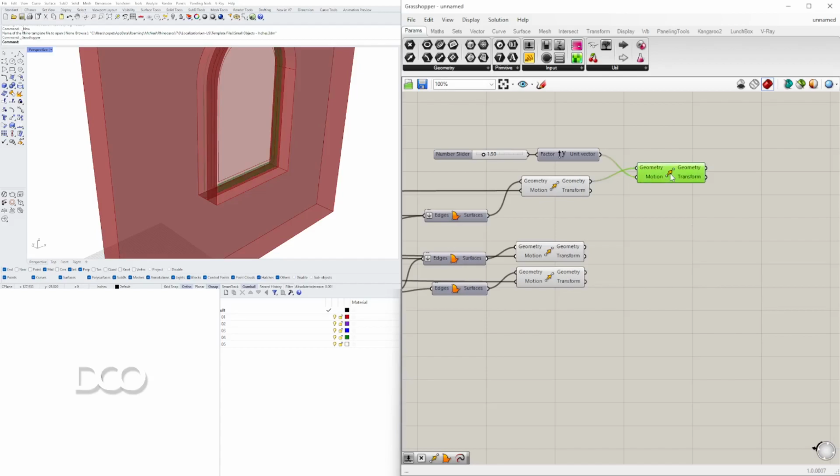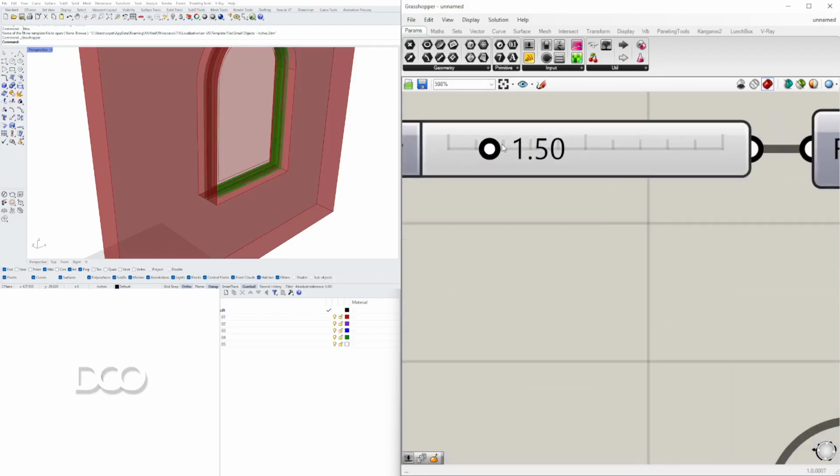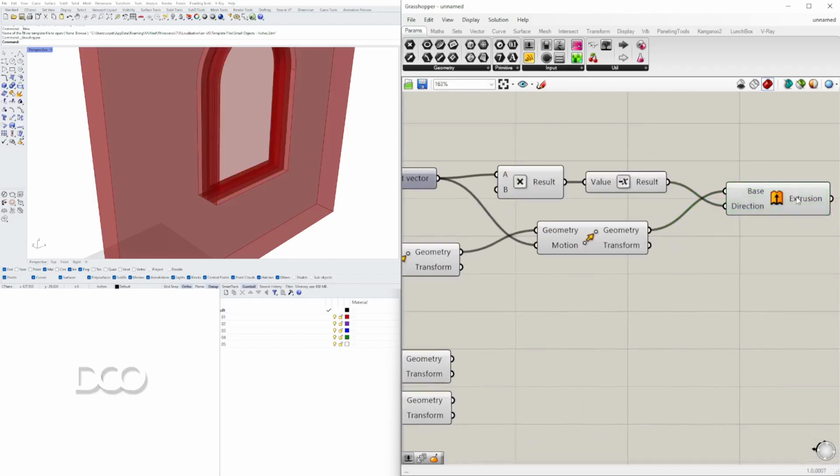So once I move it by half, then I can extrude it by that same one that I moved. I'm going to extrude in the negative direction by twice as much. So unit Y times 2, so you are multiplying a vector times 2, and then turning that vector the opposite direction, which gives us a center extrusion overall with one overall form as a result.